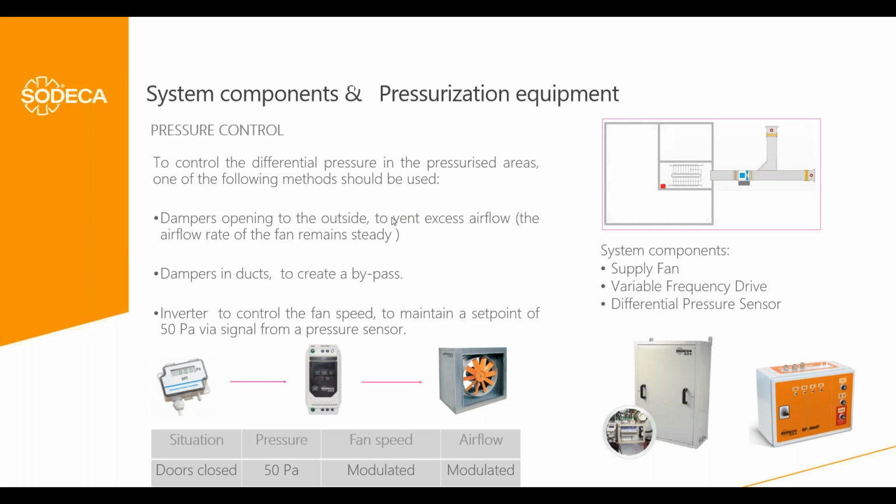So in fact, in the door closed condition, the system is not designed to maintain a specific airflow. It's designed to maintain a specific pressure. Okay, so as we have to design or dimension this barometric damper for this difference in airflows, it's necessary to adjust these dampers during commissioning, or to have dampers that allow some range of airflow. Okay, and this is a risk.